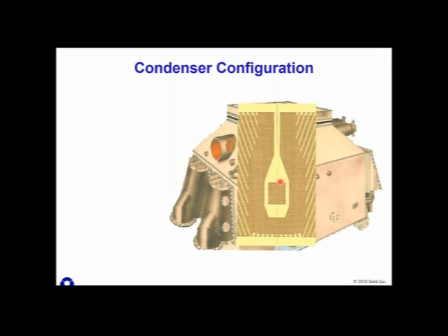They're typically made from a different material, and it's shrouded. Typically, there would be a left baffle, a right baffle, a sloped left and right baffle here, and a top hood sealing it off. And then a pipe coming down this lane to draw off those non-condensables, that air, and take out to your vacuum equipment. So this is the air cooler. And this one doesn't have any condensate management, but some do, and we'll show some of that.